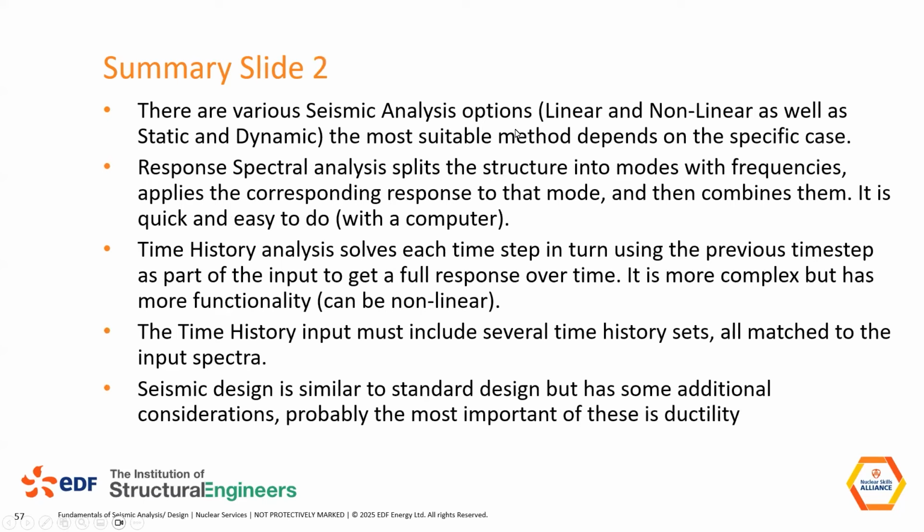We can do various seismic analyses with these inputs. A response spectral analysis splits the structure up into modes, and for each mode there's a frequency, and there's mass associated with it and acceleration, and we can work out individual responses and then combine them. With time history, we are essentially resolving the equation of motion for each time step in turn, using the previous time step as an input, and we work through the full event, so we have the full response over the event. It will be multiple time histories because we do not design for a single event.